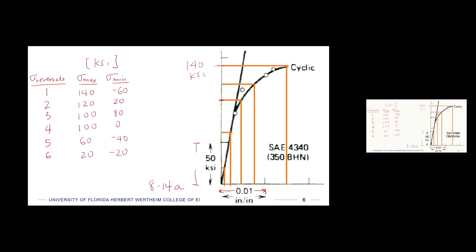The fourth type of cycle goes from 100 down to 0, so that's like the type of releasing tensile stress. Segment number 5 goes from positive 60 to negative 40, so also a positive mean stress, only slight in this one, so that's the closest to a fully reversing that we would get. And then we have, well, at a higher magnitude. And then the 6th cycle was really lower amplitude, only 20, but it is fully reversing. So we have a couple that are close to or equal to fully reversing. The other ones all have a strong positive non-zero mean stress.